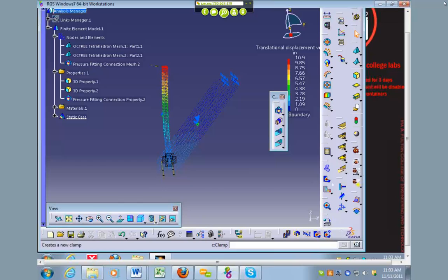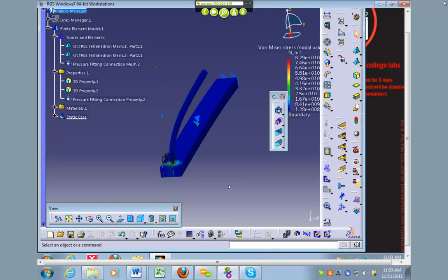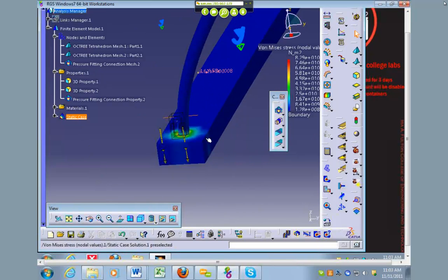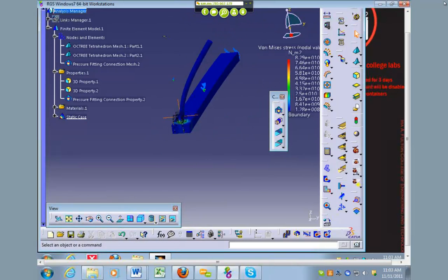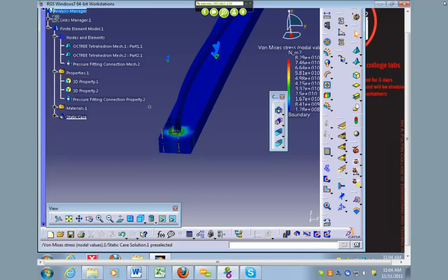I know you said it like 5 times, but I still didn't catch what the 2 load conditions were. You did a downward force like axially through the... Yeah. So if I zoom in here, I grabbed this face. Oh, you got that face as well. And I did a negative 10,000 in the Z. And you also did the sideways at the top. And then at the top, I grabbed the face at the top, and I put it in the Y direction. And it doesn't matter which direction you guys do it. I just mostly wanted to show you guys how to set it up.